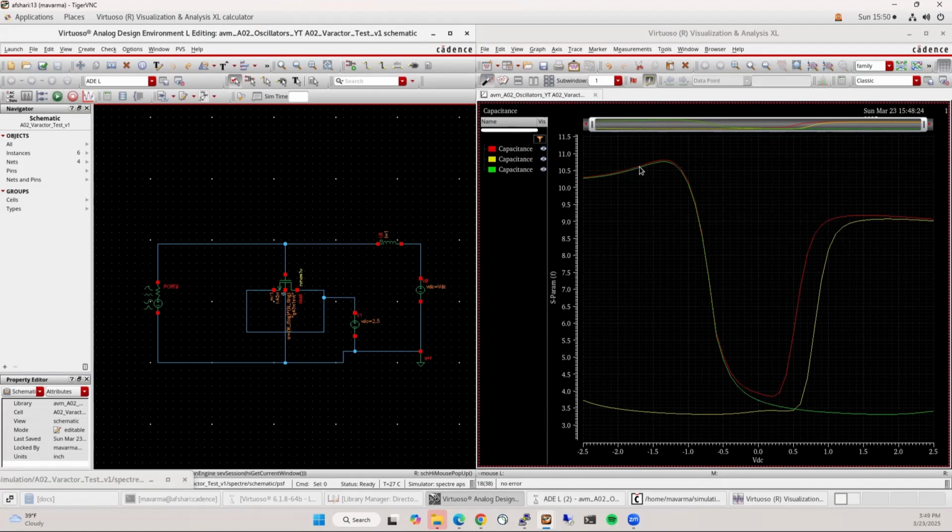So you can kind of see that this plot is a lot more smooth, right? And you get a slightly larger swing as well, and good linear response out here. Right, so that's kind of the basics behind. So that kind of verifies that you can take a typical MOS transistor and get a nice CV relationship out of it by either eliminating accumulation or strong inversion, right?